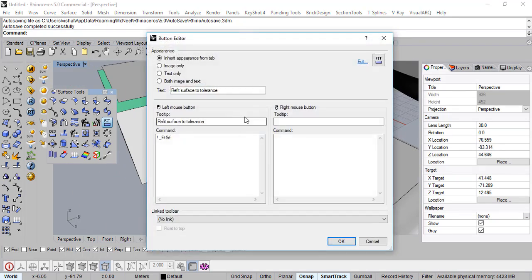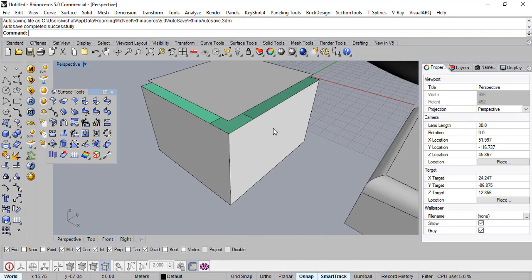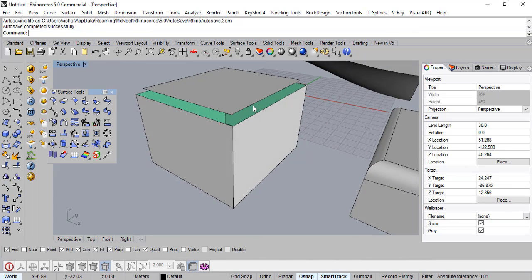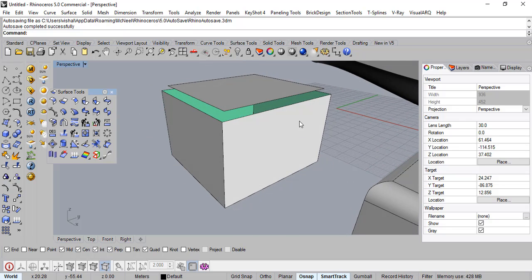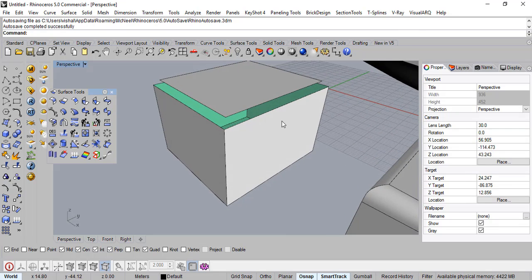Whereas over here I showed you two options. If you want to create a contour fillet, you can use that method, Boolean split, or if you just want to fillet it for individual surfaces, you can use this method. Fine. So either one works.